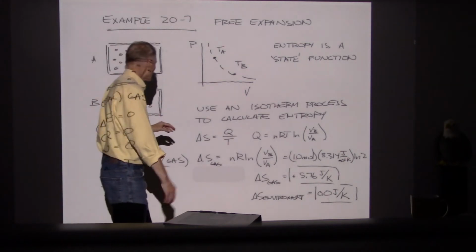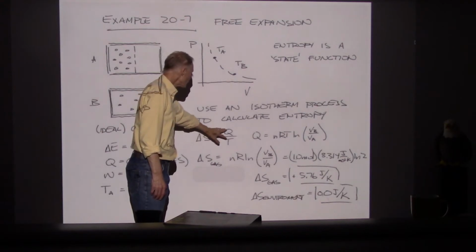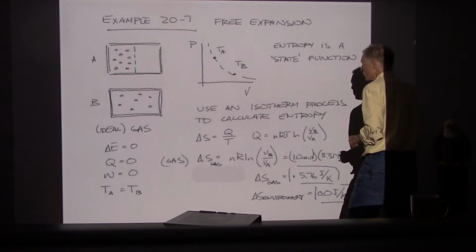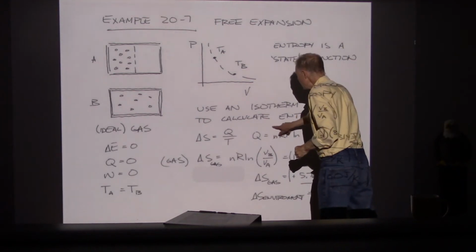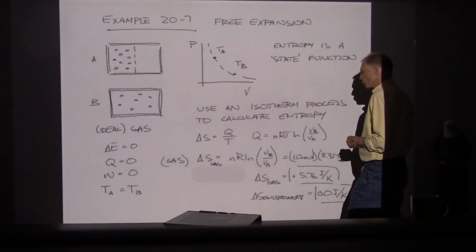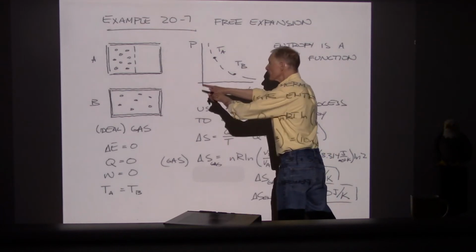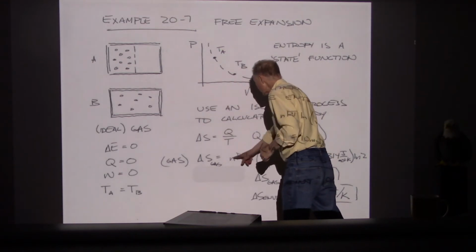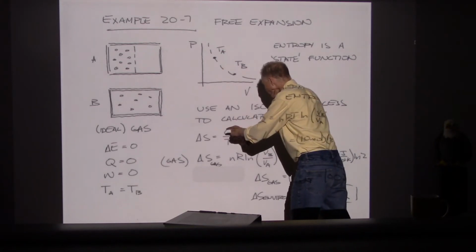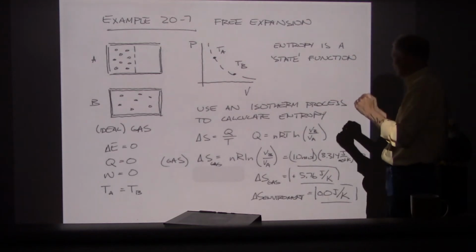All right, so we'll take an alternate route here in solving the problem. Now, for an isothermal process, if you remember, going back to the formulas we derived, the Q equals the work, and that's nRT ln VB over VA. So the entropy change that took place in those gas molecules is Q over T, and the path we took is a fixed constant temperature.